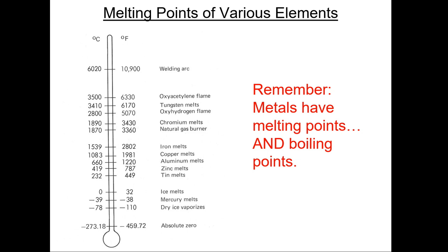I had a job in power generation years ago where we commonly welded tungsten materials. It's a little tricky, but relatively easy once you understand that it doesn't want to melt. We need an enormous amount of heat. We're using special mixtures of gases to try to bring the heat up to create some efficiency, or you're doing it very, very slow.